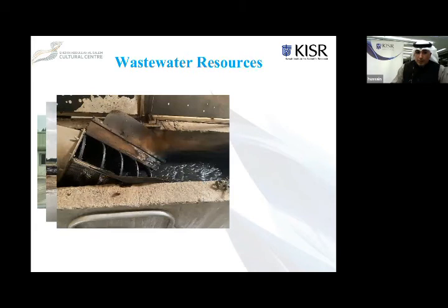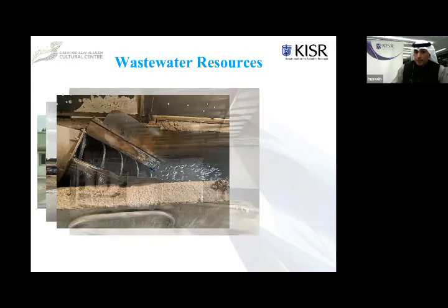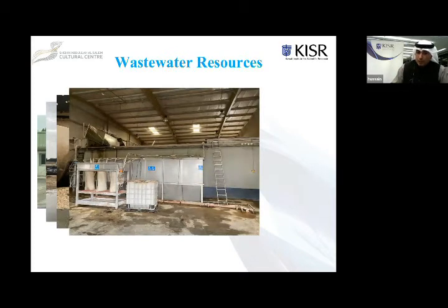The second stage, which is still the reception, is the physical separation of any objects or floating items, plastic bags, done by the screens as shown in the picture. Before the secondary stage, we also have the chemical adding process, which will cause the chemical or toxic material to precipitate at the bottom before we transfer the water to the secondary stage.